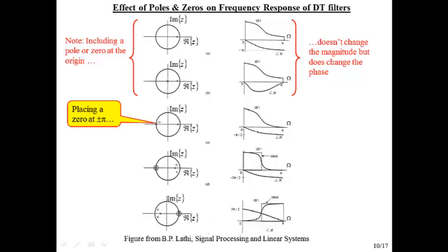Now if we place a zero over here, now that's going to affect minus pi and pi. So the distinction we see is without that zero, we didn't go all the way down to completely attenuating to zero, but now we do. So it's helping us convert this into a better low-pass filter. And if we want to continue this idea and push it even further, we can populate a few poles around zero, and that's allowing us to flatten this out more and push it out to make a nicer pass band. And then we put a whole bunch of zeros.